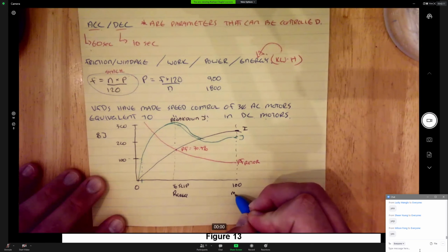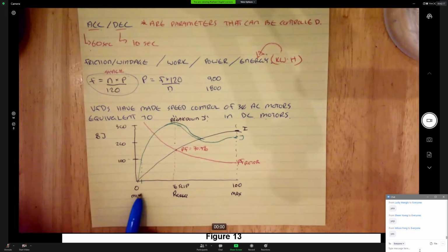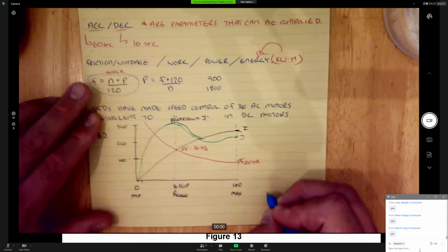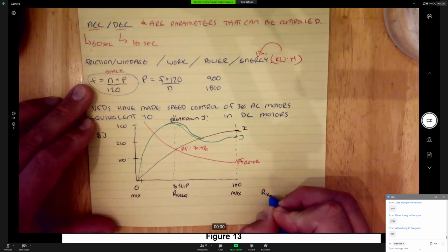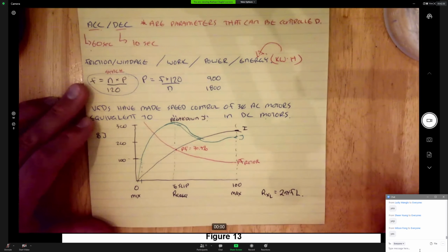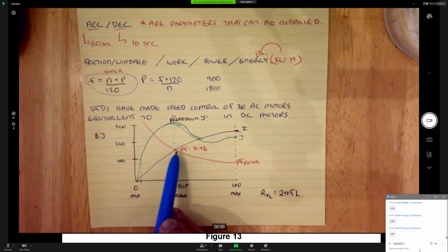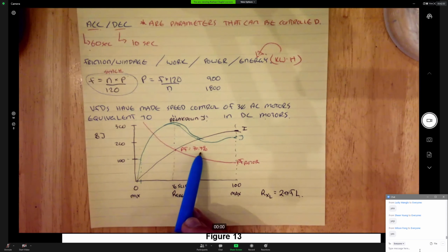The instant we energize the motor, it's at a maximum. When the rotor is almost spinning at the same speed as the rotating magnetic field in the stator, the rotor frequency becomes a minimum. As it relates to the inductive reactance in the motor, we know that the reactance is equal to 2 times pi times the frequency, in this case, of our rotor, times the inductance. So right at this point, if I said we have a power factor that's equal to 70.7,